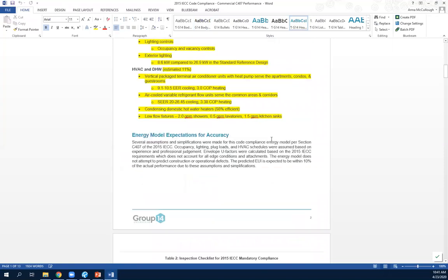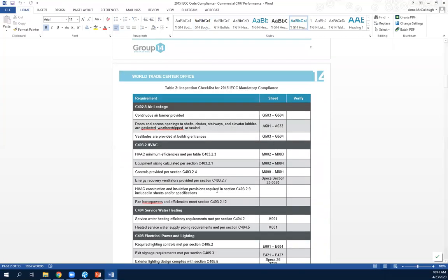We hate economizers in Texas. Luckily they fixed it in the 18. It was broken in the 15, in my opinion. You know, you could put in more efficient equipment out in West Texas where it's dry in lieu of an economizer. But in Houston, where it's super humid, you couldn't put in more efficient equipment in lieu of an economizer. And in Houston, you want to be bringing in outside air for about 15 minutes a year. So that was just broken in the code, in my opinion. But they fixed it in the 18.